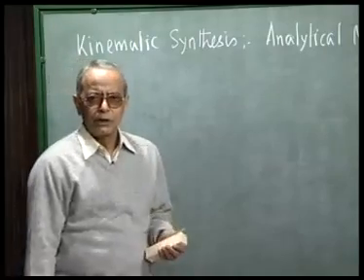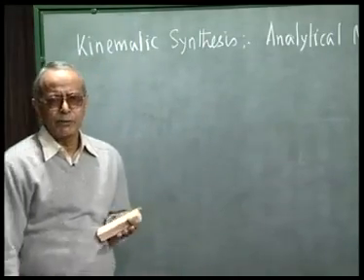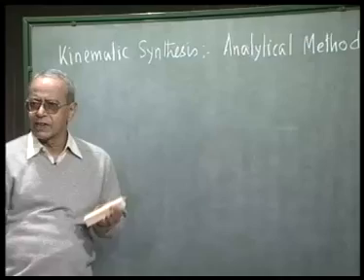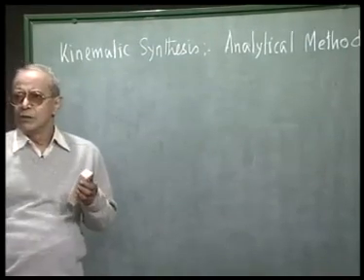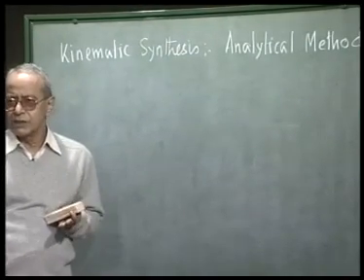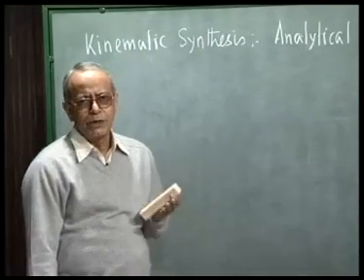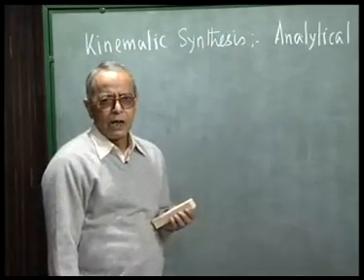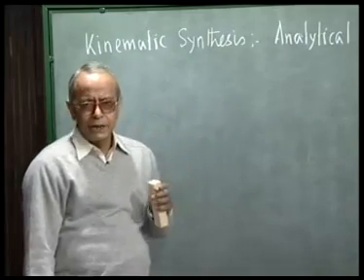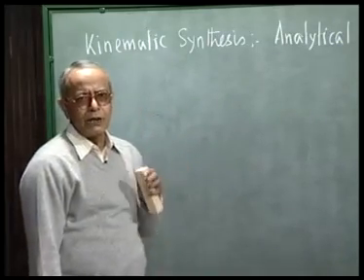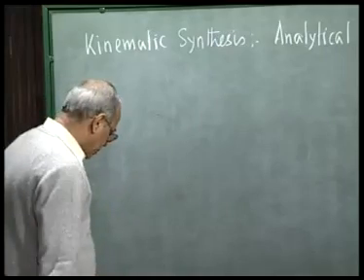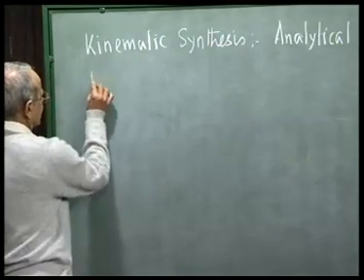If we recall, we discussed 4 different types of problems when we had graphical methods, namely motion generation, function generation, path generation, and generation of prescribed dead center configurations. However, when we discuss analytical method, we shall restrict ourselves only to one type of problem, namely function generation.